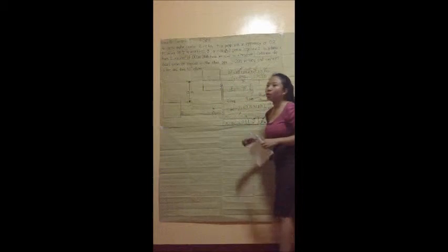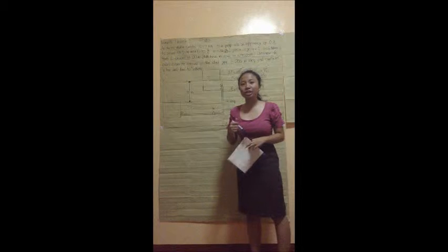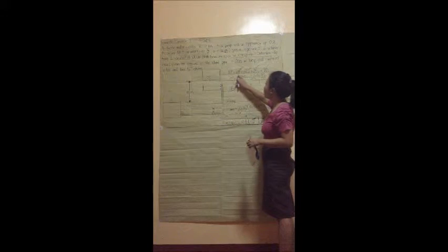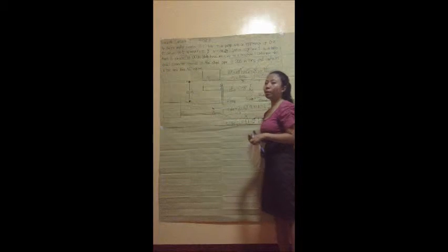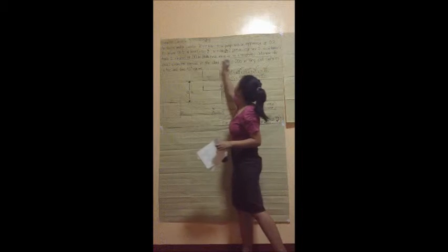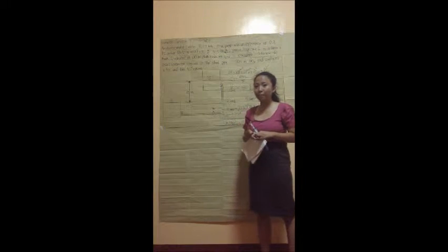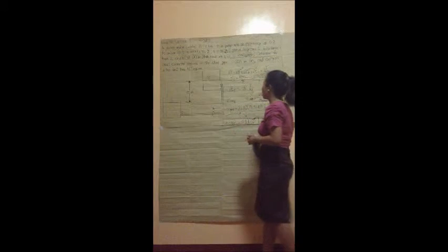So, first, we should write the mechanical energy balance. So, the friction loss plus the V delta P plus the change in kinetic energy plus the change in potential energy equals the shaft work if there is any. Based on the problem, we can say that V delta P is going to be 0 because both tanks are open to the atmosphere. So we assume that both tanks have the same pressure, which is the atmospheric pressure.